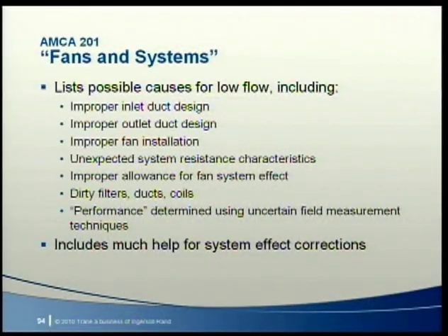AMCA 201 lists several possible causes for insufficient airflow, all of which seem to relate to either duct design, system installation, field measurement problems, or system effect. It also includes extensive guidance for proper system effect accounting.